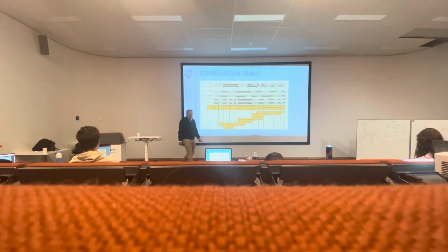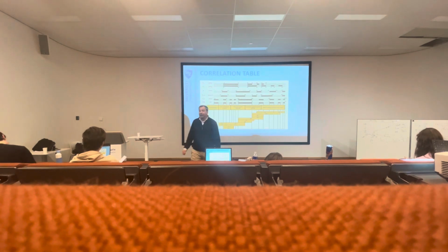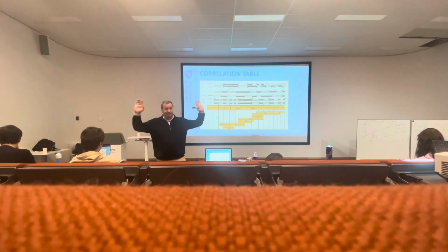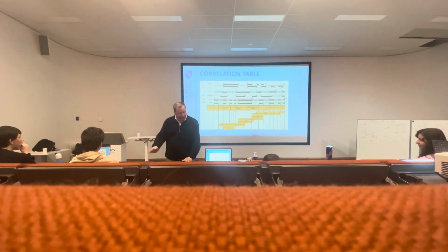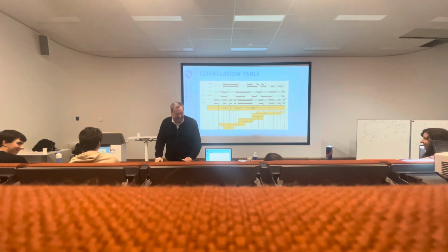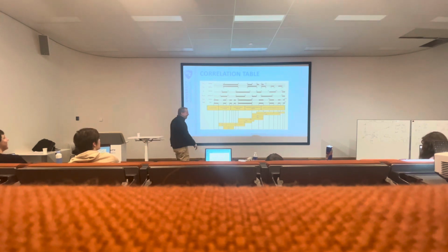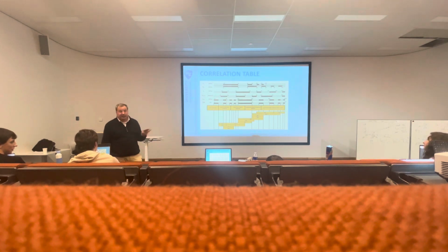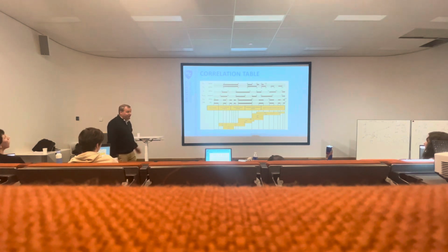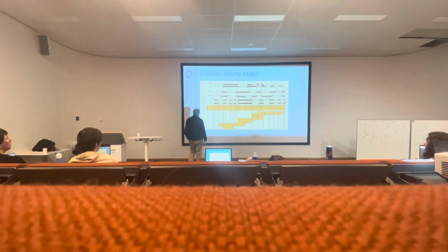Okay, so the next table is a very useful one. Put it above your bed. Take that poster of Britney Spears away. Alright, so that table is very useful because later in your life, when you get some input data, let's say you have a CBR value of 5%, then you can estimate that the E dynamic will be about 50 MPa.